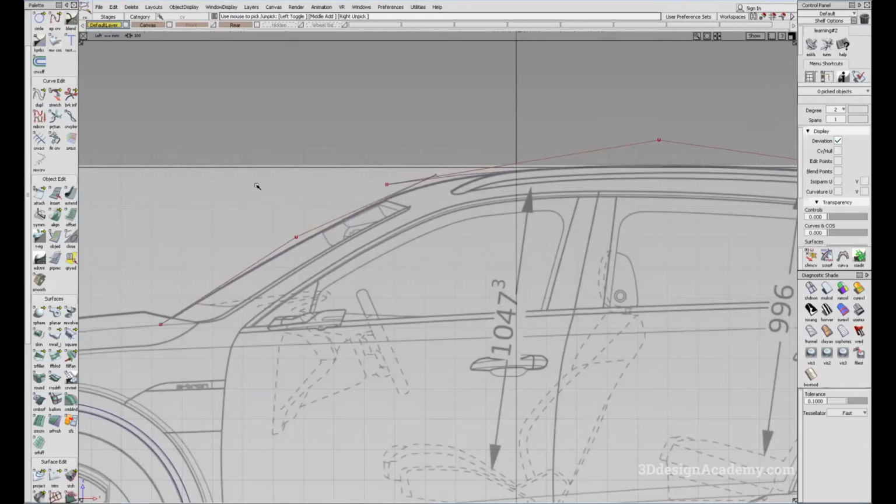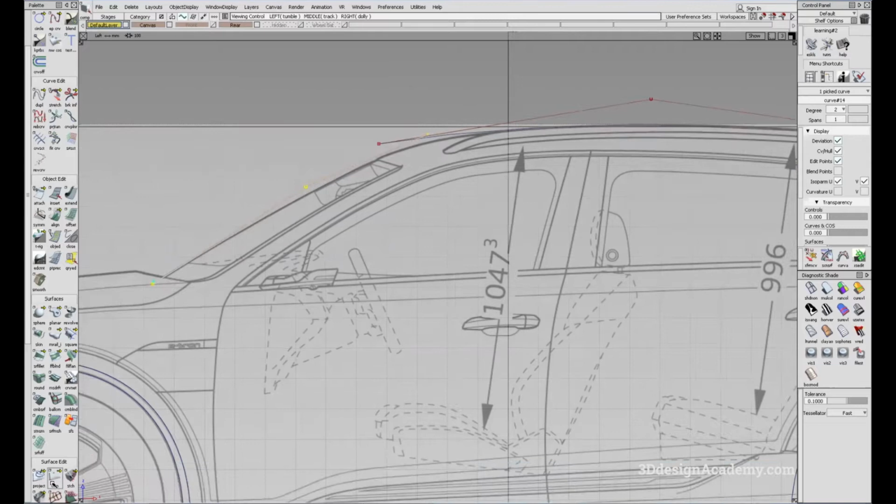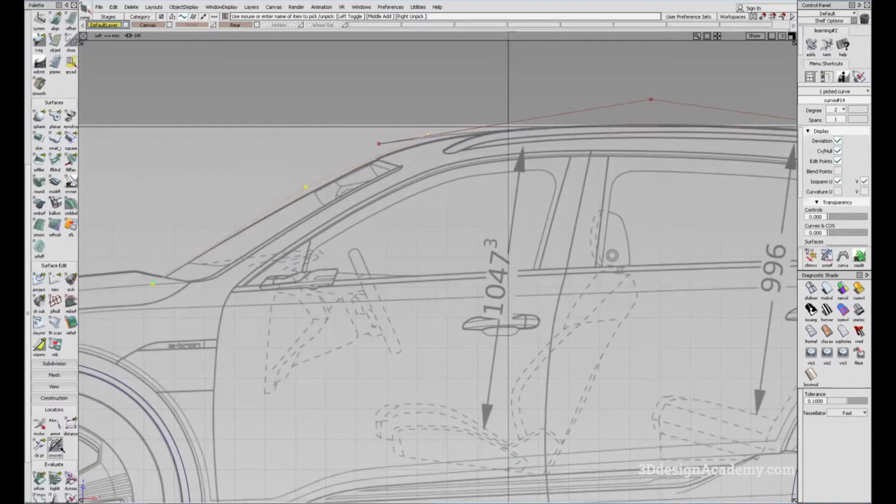the fillet. So what I'm going to do is grab the transform CV tool. I'm going to grab slide and pick the CV here, and move it slightly. I'm going to have a slight lean towards the top to help the curve have a little bit of acceleration. Now, what am I talking about when I say acceleration?